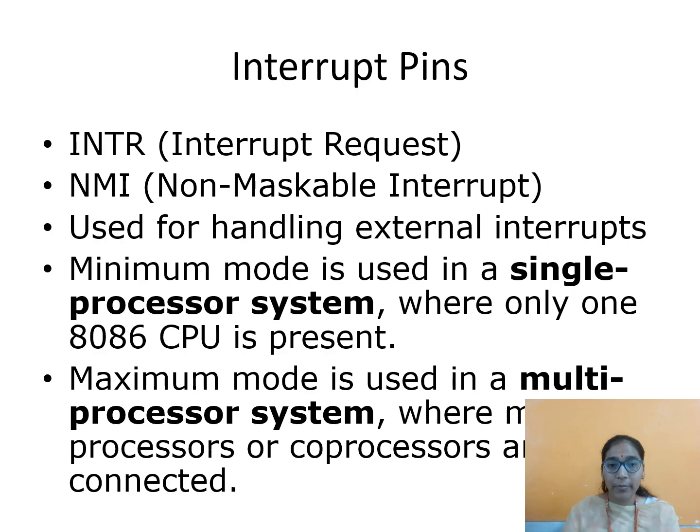Interrupt pins. The interrupt pins are INTR interrupt request, NMI non-maskable interrupt, used for handling external interrupts. These are the interrupt pins used for handling the external inputs. And there are two modes of operation in 8086, maximum mode and minimum mode. The minimum mode is used in a single processor system where only one 8086 CPU is present. The maximum mode is used in a multiprocessor system where multiprocessors or co-processors are connected to the 8086 processor.